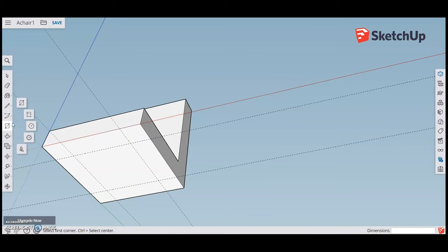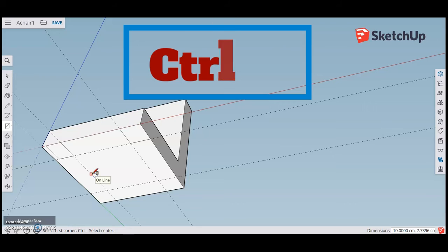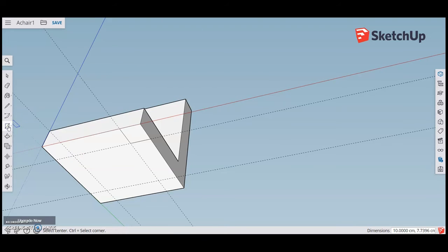So click on now your rectangle tool again. You'll see an intersecting point in X where you get right to where that dotted line and your existing edge cross. Just click once and we're going to draw a quick square. Now we need to do that for all of our legs, so the other 3 as well. So do that quickly. And if you make a mistake like I just did there, not a big deal. Control Z is going to be your best friend. Tap Control and Z one time, and that will immediately back you up so that you can hopefully grab a new square here to complete our object.